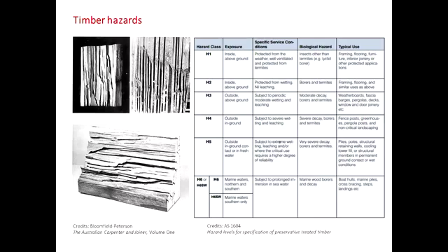So these are tunnels developed by termites. You won't see them. You need to cut the timber in half, but it will make your product incredibly weak. Imagine that's the joist that's on top of your head. It will suddenly collapse without giving you any notice. So that's why we need to treat timber to make sure the termites won't eat it. All right? We don't want to have those tunnels.